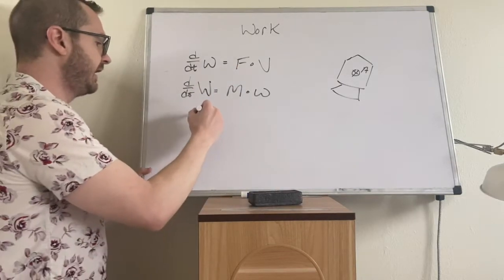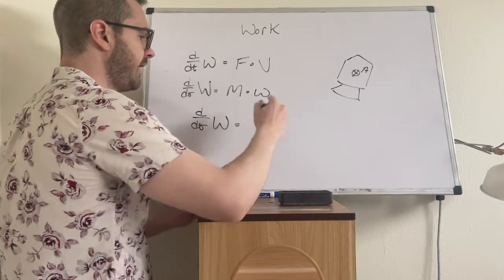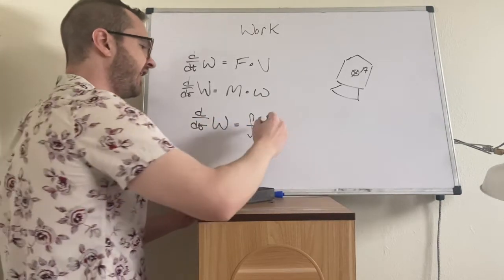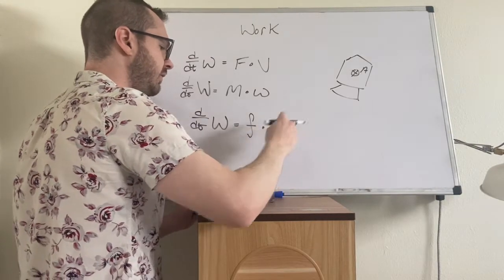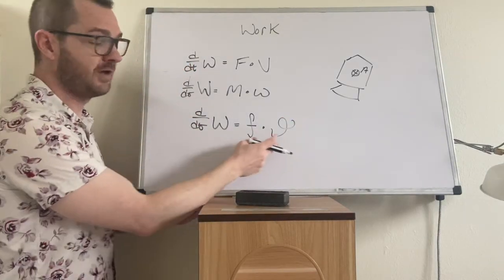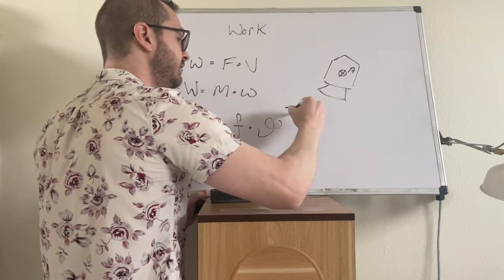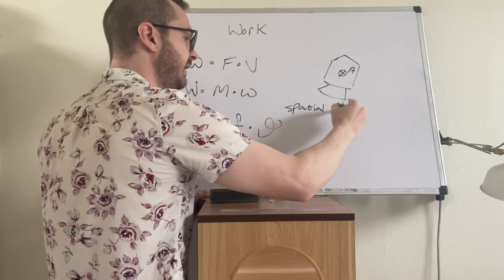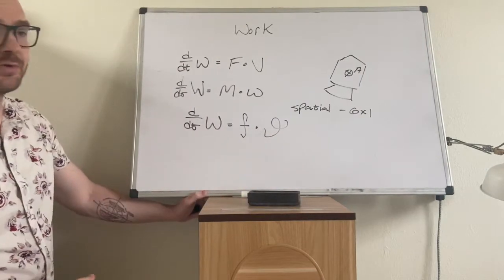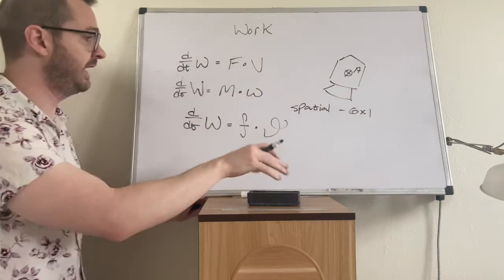Let's combine these, and let's say that the total change in the work is equal to, and I'm going to write this as a lowercase script f dot, oh, it's kind of a weird one to draw. There we go. So this is called var theta. These are spatial notations. So spatial being 6-dimensional, so I'll say 6 by 1. It's a 6-dimensional description of the problem, and really what we're doing is we're stacking these two equations together.